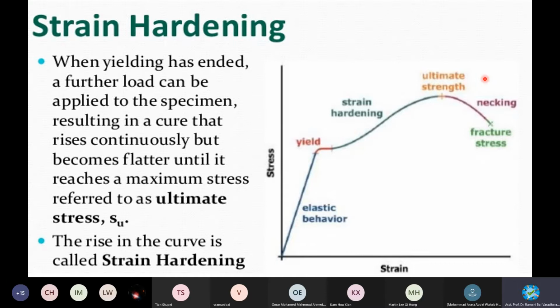The original curve will be a little bit higher, due to the material property. But because you are using testing equipment, you have a kind of curving in nature. It is supposed to be flat, a constant value with no load applied, but the strain rate is increasing in this direction until it reaches the ultimate strength, which is the total strength of the member, or what we decide is the capacity of the member. From that point onwards, the failure starts. The name of the failure is called necking. A kind of necking starts, a reduction in the cross section until it fractures. Okay.